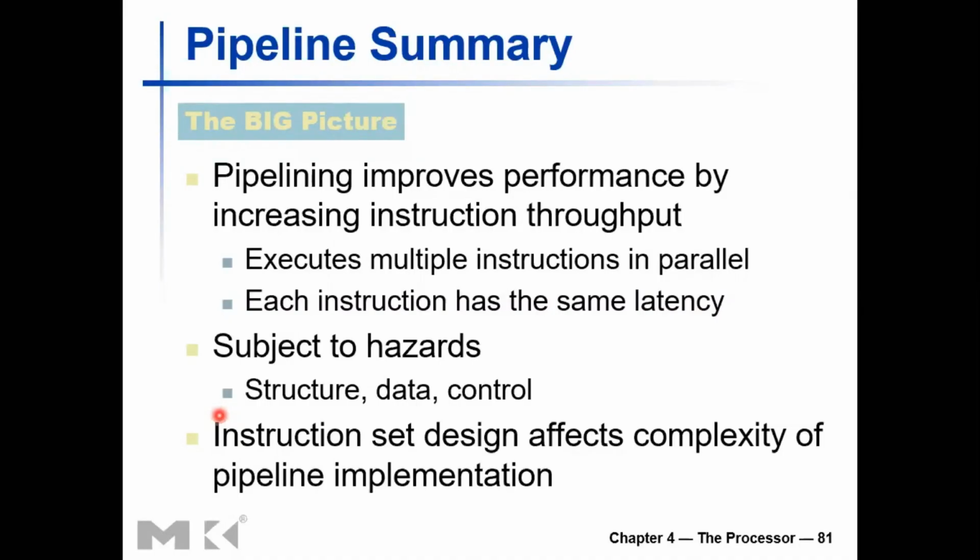You don't get a throughput increment as much as that because there is a limit to how much you can exploit instruction level parallelism. You cannot keep a steady pipeline running with that many stages. You will have to flush the pipeline, you'll have to stall a lot. So your benefit is not really 30 something times compared to a single cycle, or 4 or 5 times compared to, say, a 6-stage pipeline, right?